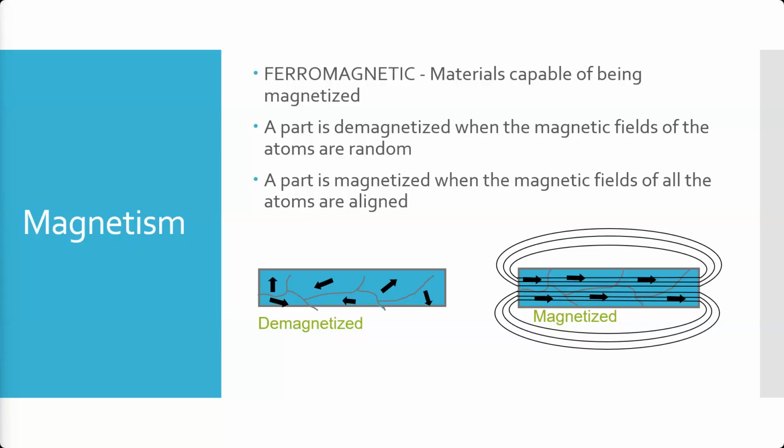And so magnetic particle inspection relies on this ability. And like I said, with ferromagnetic parts, once we magnetize them, it depends on some factors, but they tend to stay magnetized. So that's where we have to demagnetize it when we're done. We have to re-scramble this magnetic field so that the part is no longer magnetic. Something like stainless steel, in a lot of cases, the poles will align while the magnetizing force is present, while we're running current through the part or putting the part in a strong magnetic field. But as soon as we take that away, they re-scramble on their own.